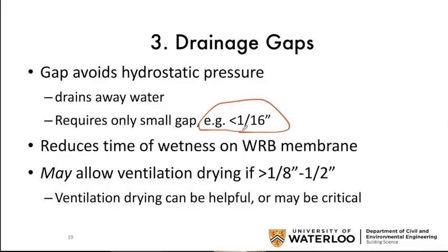So it's quite small. And often we have many successful systems that rely on accidental gaps, meaning they're formed by 2 materials coming together, and the nature of the 2 materials is such that there will always be some gap between them. And those gaps are hard to measure because we don't intend them. But when tested, realistic gaps like that, such as corrugated sheet metal applied directly to building paper on your garden shed, they work. They work to drain water. And so those gaps are pretty small.